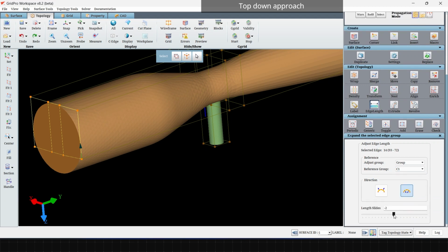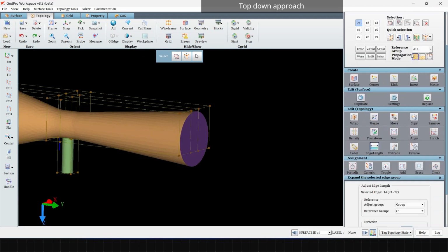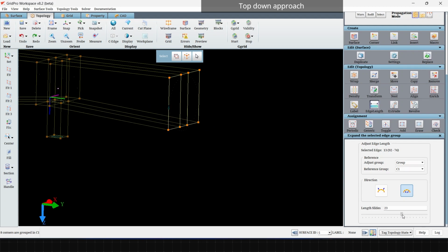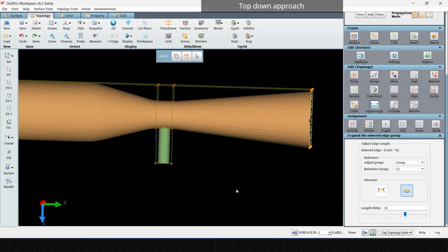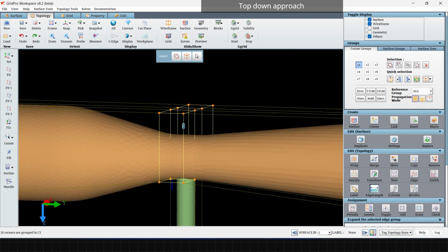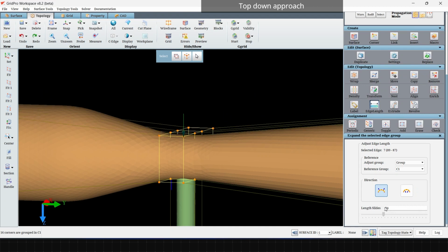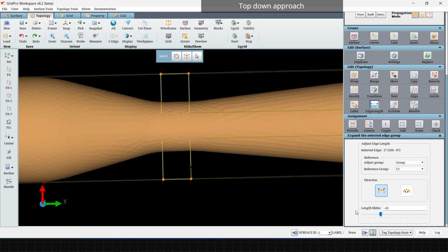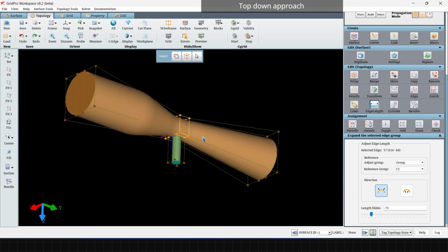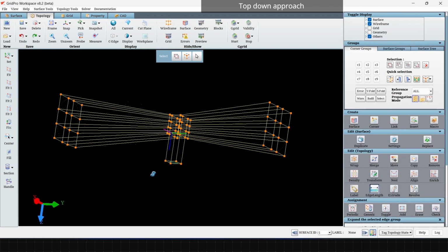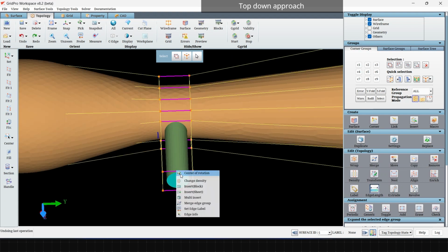The corners are now being repositioned using the edge length option. This gives the grid smoother a much better initial positioning, which speeds up the grid smoothing process. Some additional inserts are being added, which will help us later on to exclude the block faces while creating the O-grid.